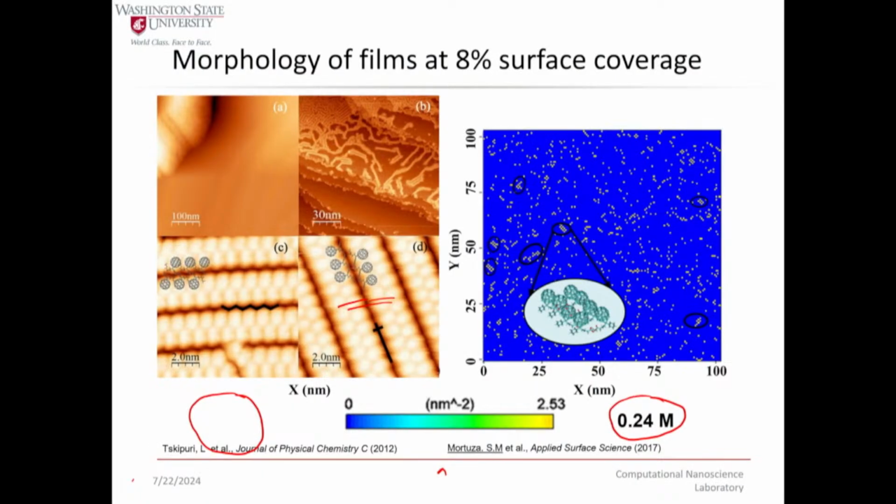Yeah. But the challenge with tandem is you have more interfaces, and as soon as you have more interfaces, there will be more losses, including recombination. You can get to very high theoretical efficiencies with tandems. So yeah, I mean, the photovoltaics community is certainly exploring perovskite-based tandem solar cells.